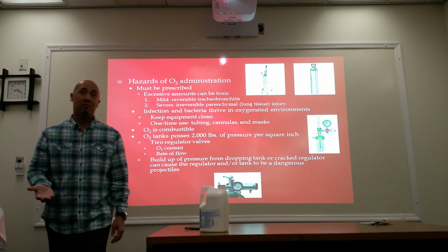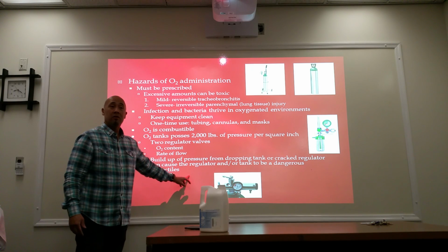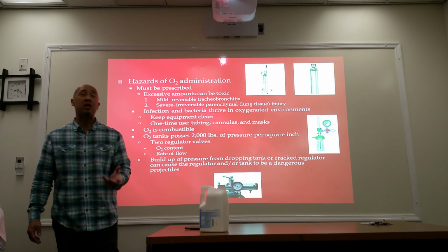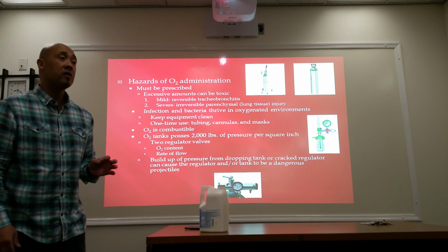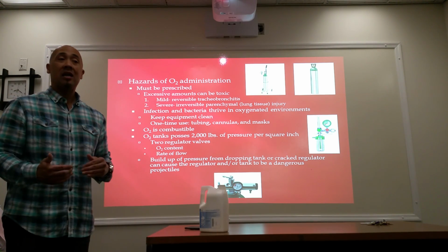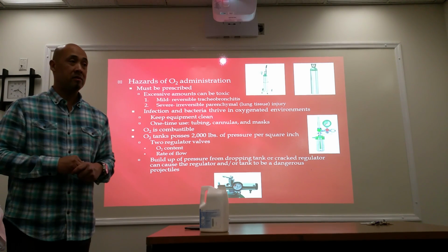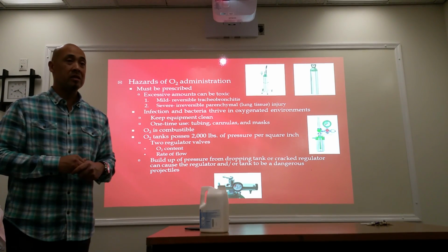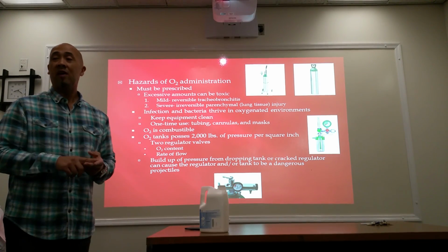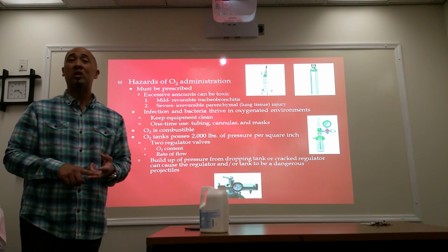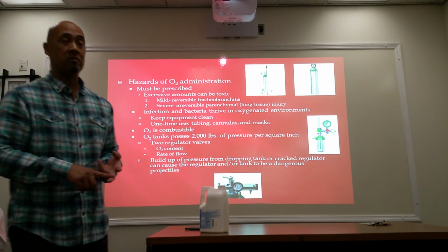So it's your responsibility to make sure that you have a full tank at the beginning of the day. Your other valve is going to determine the rate of flow. The rate of flow is written as liters per minute, LPM. Okay, liters per minute. So again, two valves, one to determine the amount of oxygen in the tank, and the other one to regulate oxygen flow.